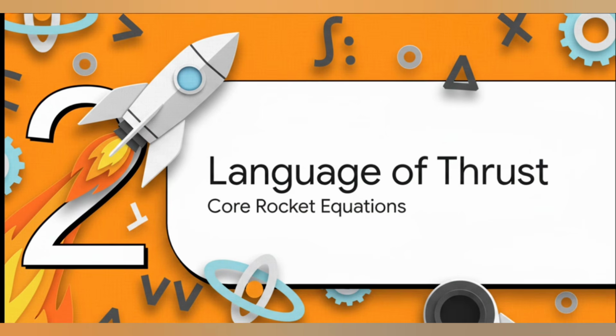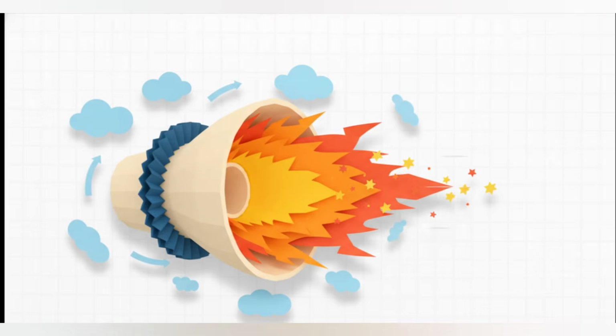Well, that's where the language of rocket science comes in. To really design, build, and fly these things, engineers rely on a handful of core equations. And this right here is the big one, the thrust equation. Now, I know it looks a little intimidating, but it's really telling us two things. The first part is the core of Newton's law. It's how much stuff you're throwing out the back times how fast you're throwing it. The second part is what we call pressure thrust, and you can think of it as a little bonus push the rocket gets when its exhaust pressure is higher than the air pressure around it.